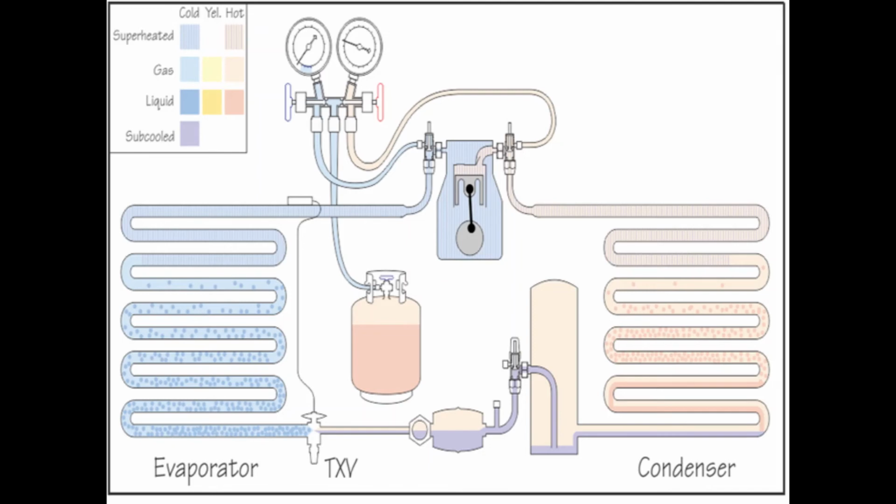And then during charging, the high pressure side of the manifold should be closed because there is no need of opening the high side of the manifold. We are dealing with only the low side of the manifold because it is vapor charging, not liquid charging.